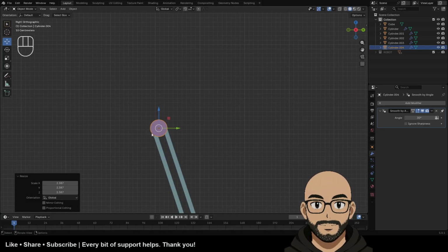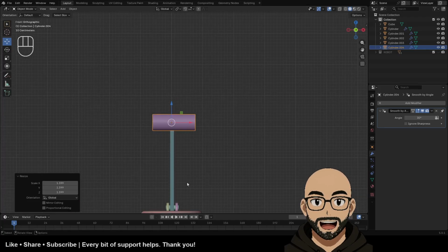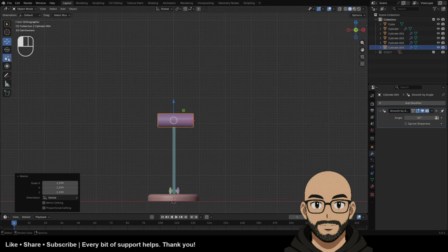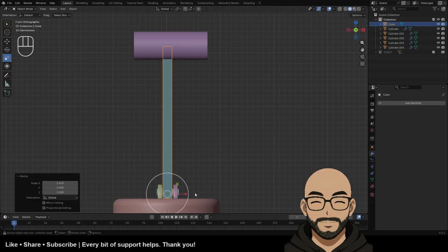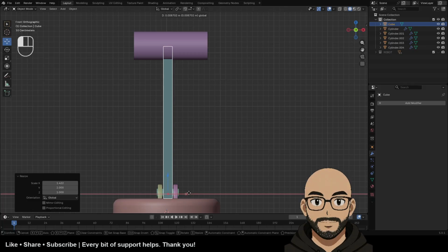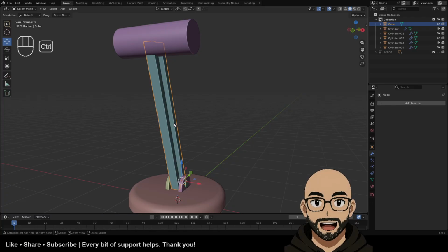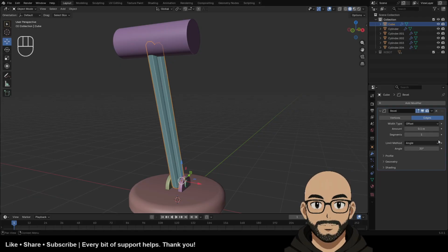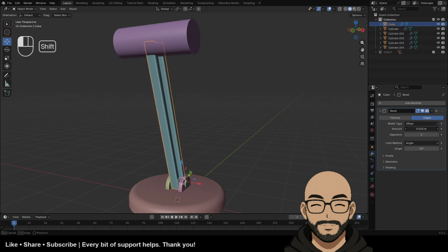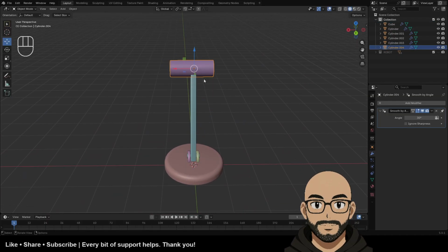So Shift D to duplicate, kind of fill this in. And of course, we don't need it this thick. This could be thicker, to be honest, not this. There we go. And maybe we can center this more. There we go. And we could also perhaps just Control A, apply the scale, add a bevel on this. There we go. And shade auto smooth. That looks a lot nicer.